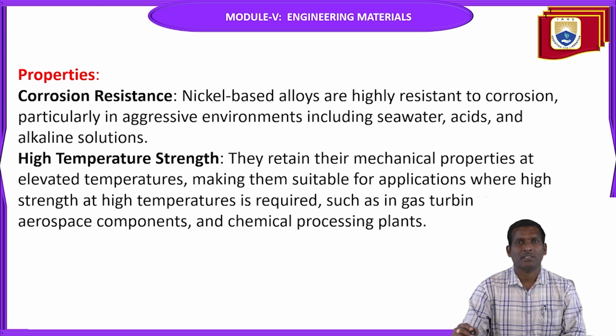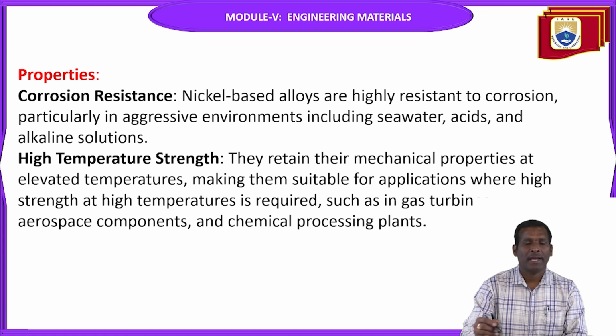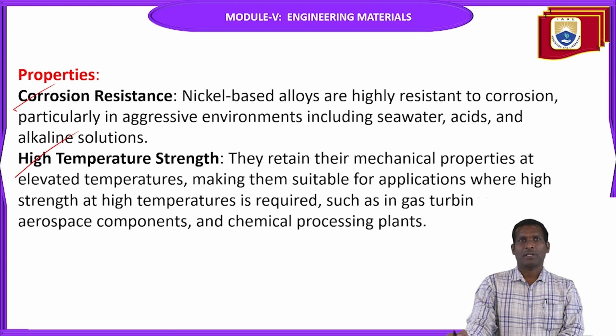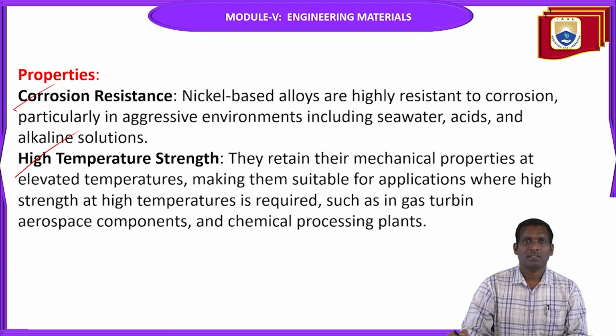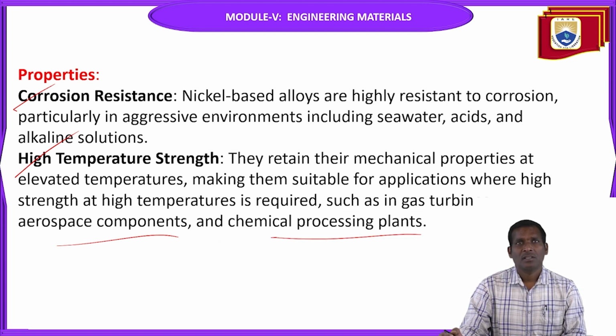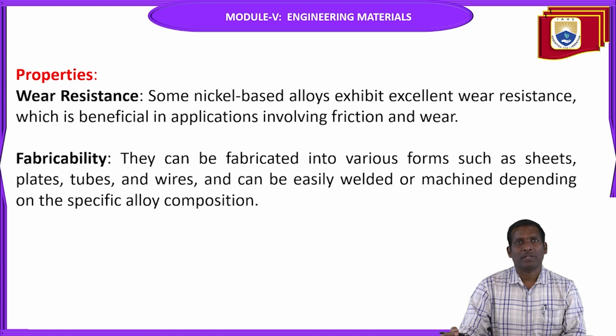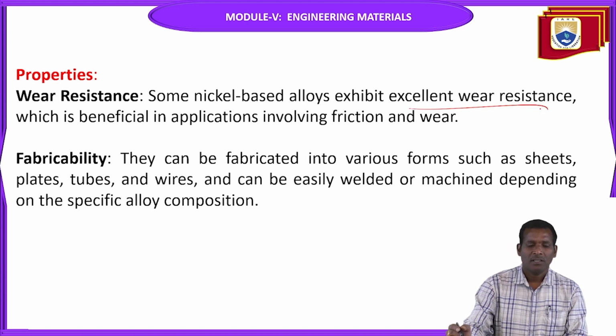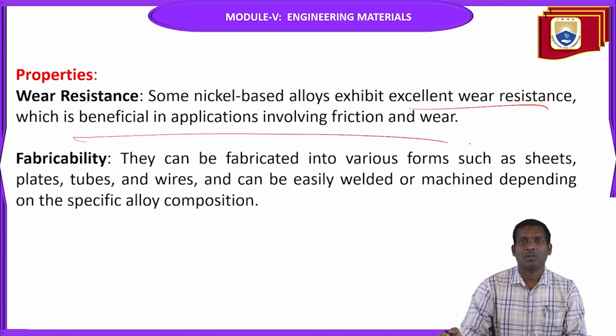Whenever these types of solutions are present, it can withstand the corrosion. Then high temperature strength: they retain their mechanical properties at elevated temperatures, making them suitable for applications where high strength at high temperatures is required, such as in gas turbines, aerospace components, and chemical processing plants. The wear resistance property: some nickel-based alloys exhibit excellent wear resistance, which is beneficial in applications involving friction and wear.